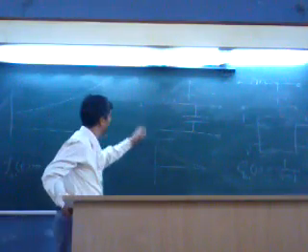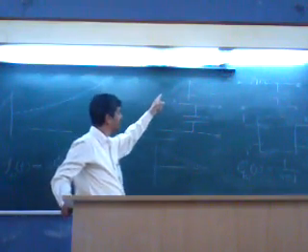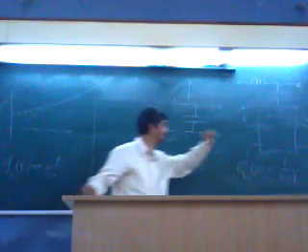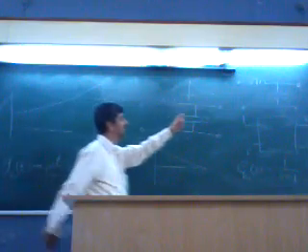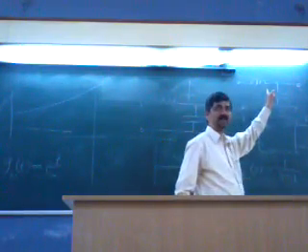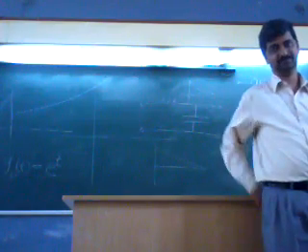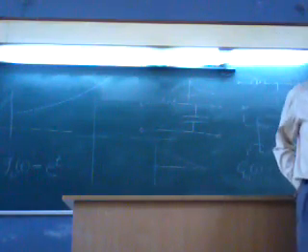Here, when I give the impulse, the impact goes down. Here I give the impulse, the impact continues to rise. Here I give the impulse, the impact neither grows nor dies. Is it clear now? So it is the pole's position that is describing to us the type of the system. The position of the poles.